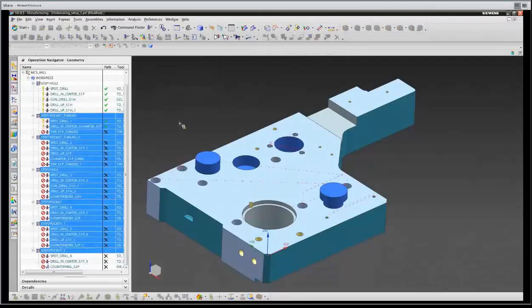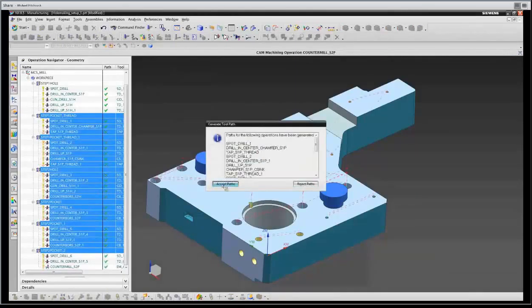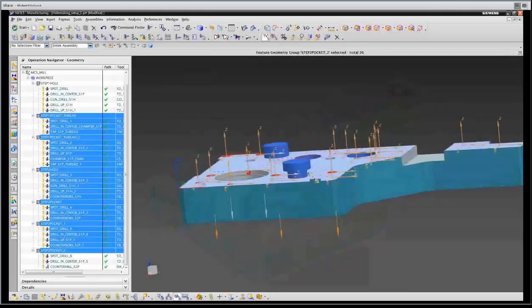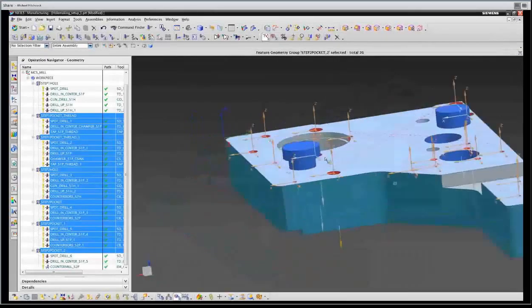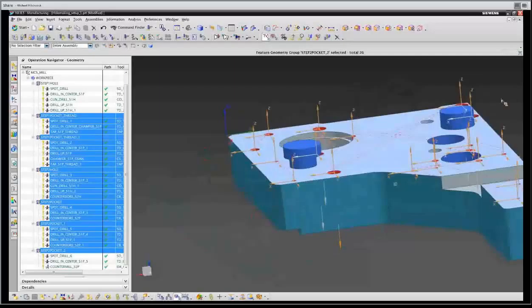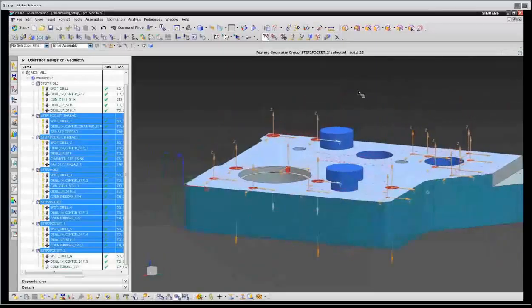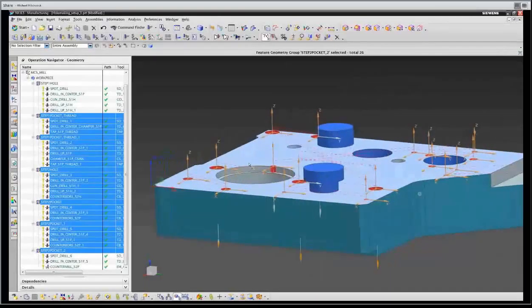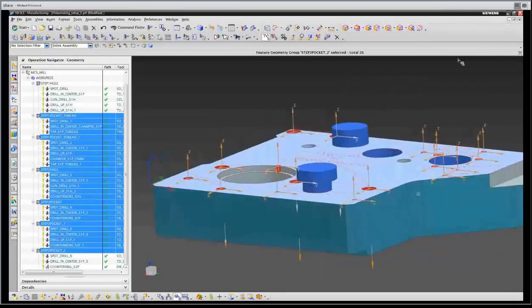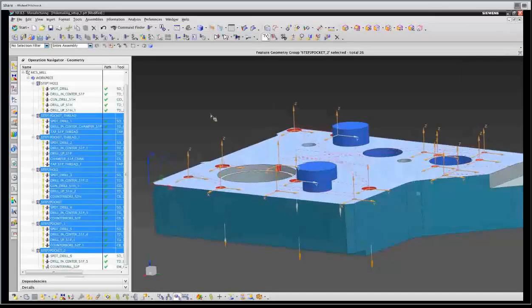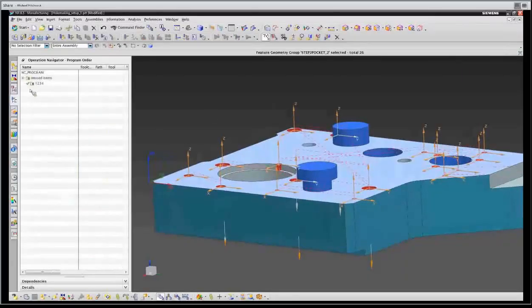Through. And we've got some smart things going in here. These things by default are set to recognize the part and know what's there. You'll see that when we're drilling holes in the areas of this boss as it's standing up, we recognize when we go across those bosses and we need to pick the tool up, and when we can just go straight across at lower levels to drill these features and all that. So there's some smart things going on in there.